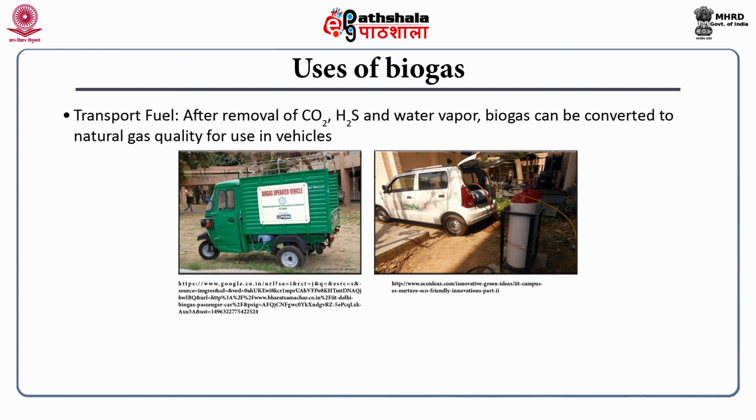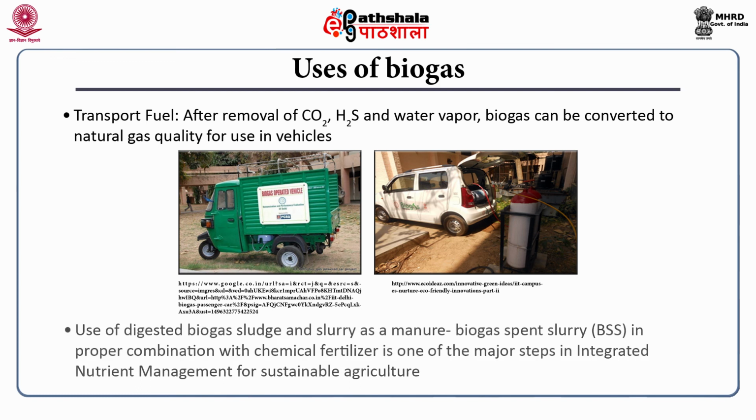Several operating strategies are already investigated with these air fuel ratios for a stationary engine. The carbon dioxide emissions are also less for these biogas fueled engines. Apart from this, it can also be used as a fertilizer. The recovery of the plant nutrients from the biogas plant: the biogas spent sludge has various nutrient content in it and is a rich source of nutrients for the plants. And it gives an economic return to the farmer using this biogas technology.